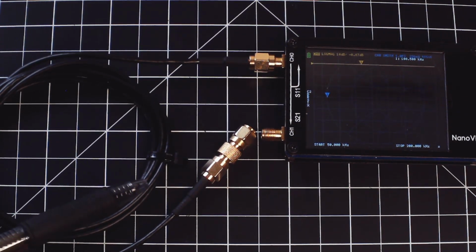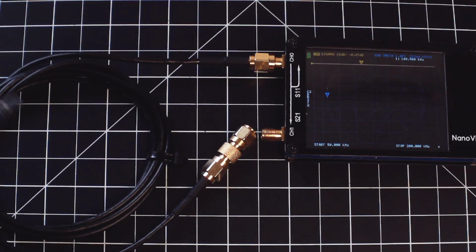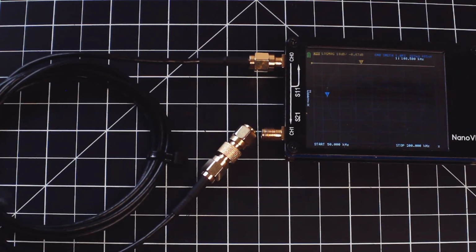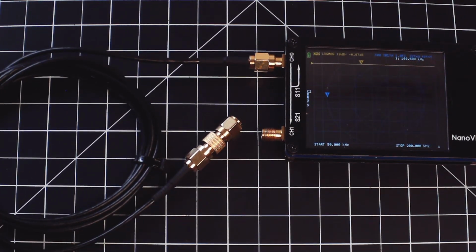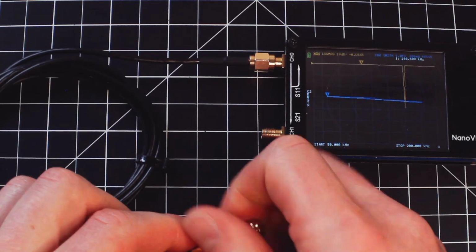The problem, though, is that you can't just crank up the frequency and do this measurement, because then you'll have the phase issue to deal with here in terms of that phase error accumulating as the signal goes down and back. So yes, this is actually an accurate measurement, but we need some way to characterize this thing at higher frequency. That is to say, we can't trust our inductance measurement at low frequency or expect it to remain consistent as we go into higher frequencies. So instead, what we're going to do is measure the velocity of propagation at a high frequency. So this is accomplished as follows.